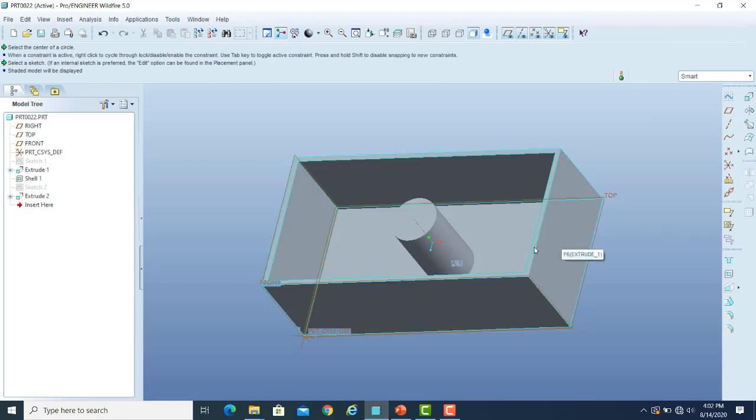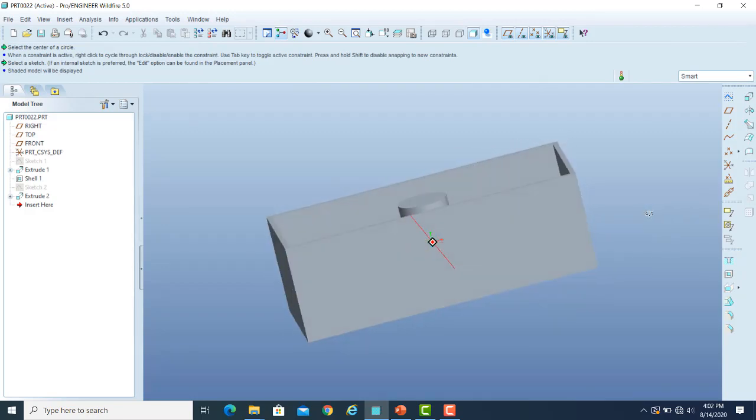So what I am going to do is that I will make a line which will start somewhere from this cylindrical surface of that circular extrusion, and I will extend that line up to the base of that tank, so that I have a closed region, and then later on I will be able to use the ribs feature. So you will understand when I first create the ribs, then we will discuss it further. So let me draw a simple straight line.